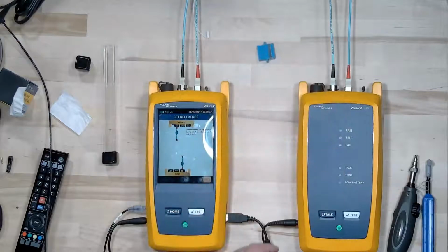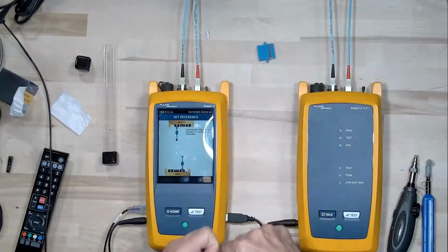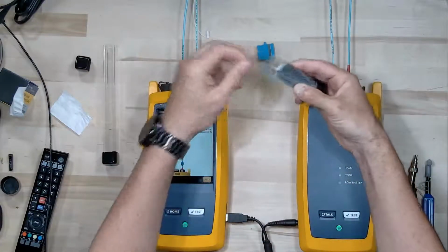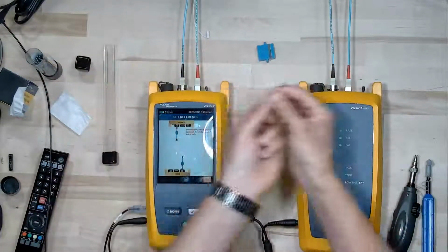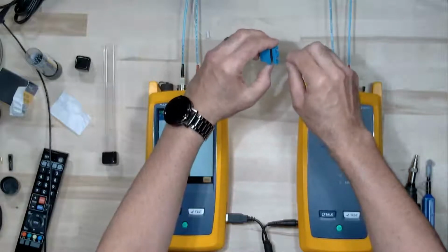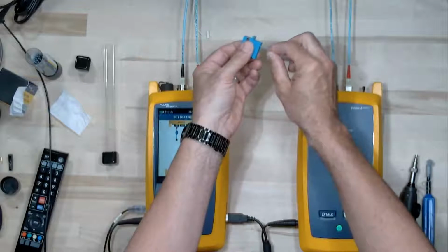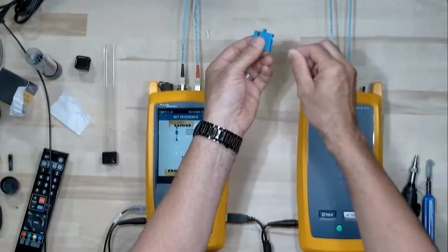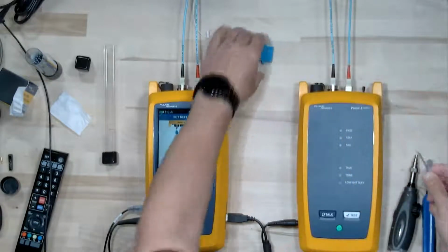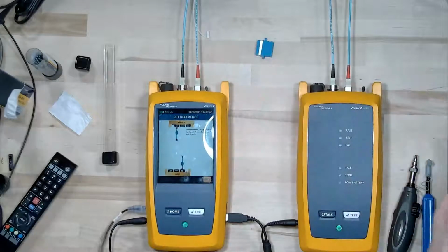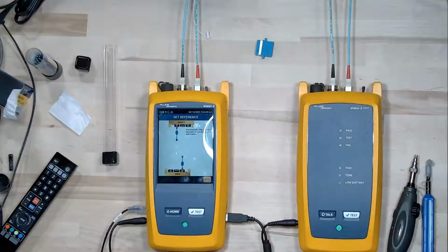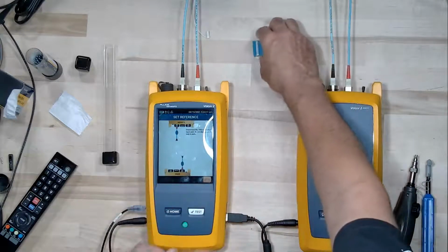And I'm going to show you a trick that I have figured out that has made setting reference so much easier. And that is, I'm going to grab a fiber cleaning swab right here. I'm going to take that swab. I'm just going to give this bulkhead connector just a little clean. I'll tell you, in doing these classes, getting some dust in this bulkhead connector was one of the biggest challenges, and it caused me to have all kinds of problems setting reference. So I found that by cleaning that, it solved a lot of the problems. Now, what I want to do is take this swab, now that I've used it, that goes in the garbage can. We don't reuse that for anything.